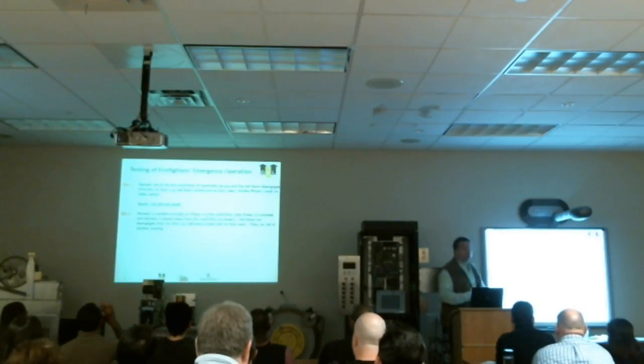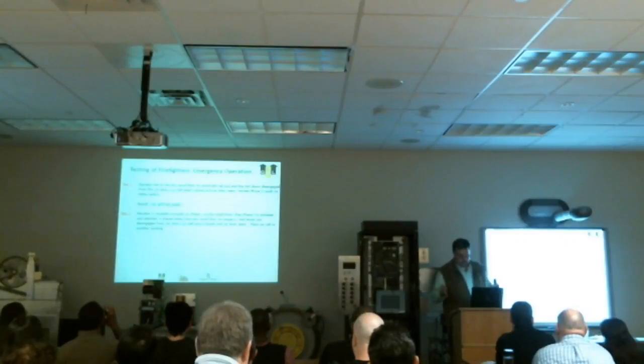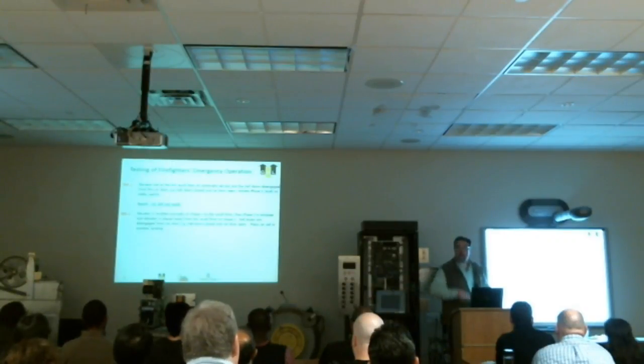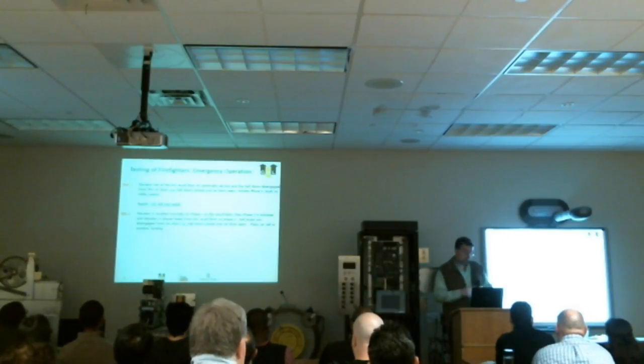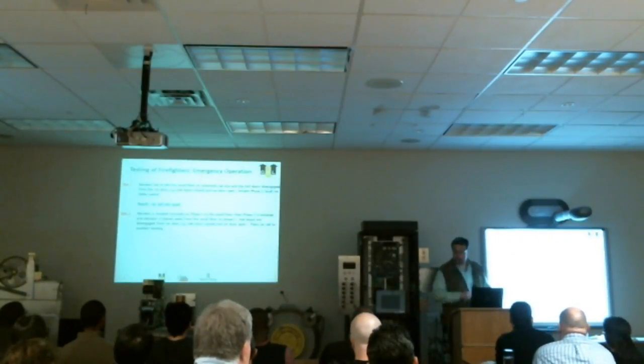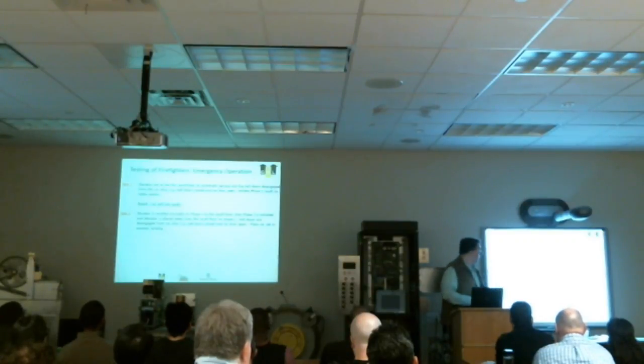Second test that they do. They recall the elevator normally on fire phase 1. The fireman gets inside the elevator, puts it on phase 2, and then takes it to another landing, someplace else. Now the door is open. Now the landing doors are bypassed. The car door is now disengaged from the landing door, so now we detect the fault. Meaning that the hall doors are made, but not the car doors. What should happen?